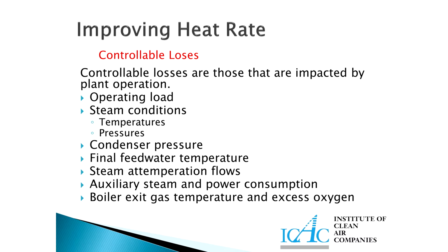The steam conditions, very simple. The higher the pressure and the higher the temperature of the steam, the better efficiency you'll get, because the steam has more energy for the same amount of heat energy that you're putting in. The condenser pressure.